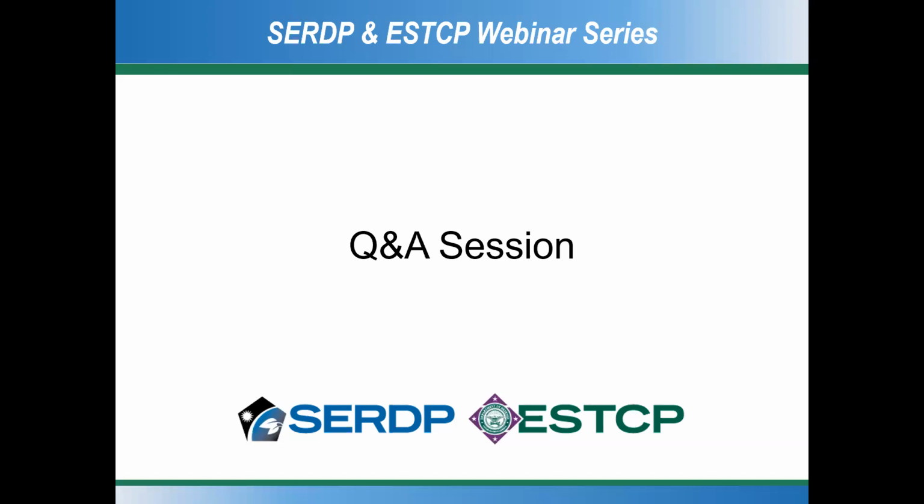Thank you. And the last question for you is just a request to please recap what kind of geological information is needed to support the design of the system. Yeah, that's really important. As I pointed out, you basically have no ability to control the well design in the field. So you really have to know ahead of time exactly how you're going to install it. And so I would say in most settings, you're going to want pretty high resolution information on permeability so that you know your target lithologies. And in some settings, those target sand zones might only be a couple of feet thick.